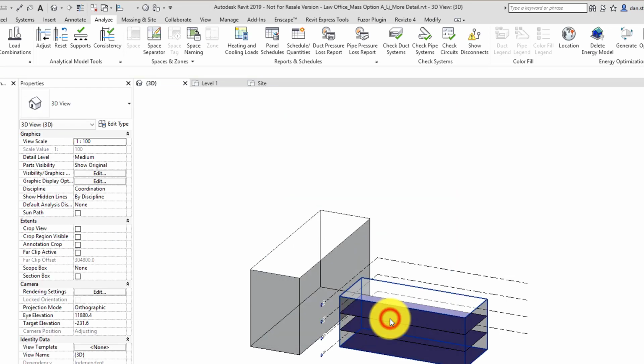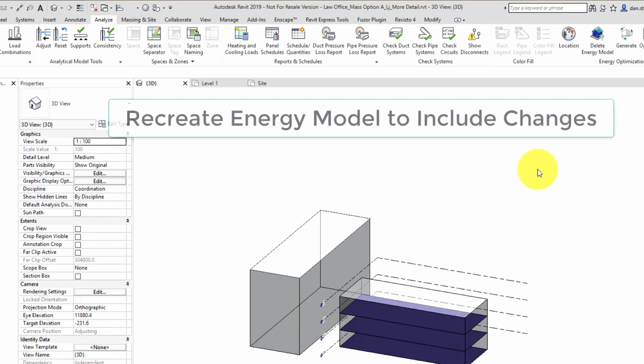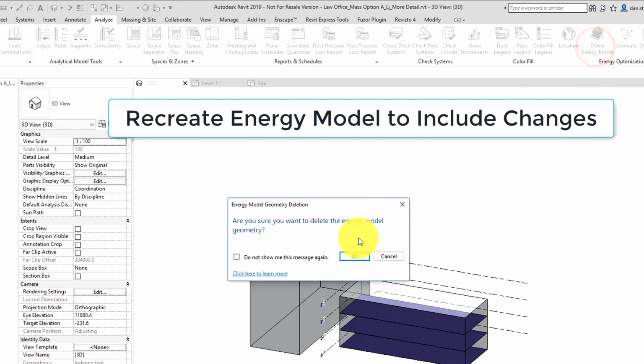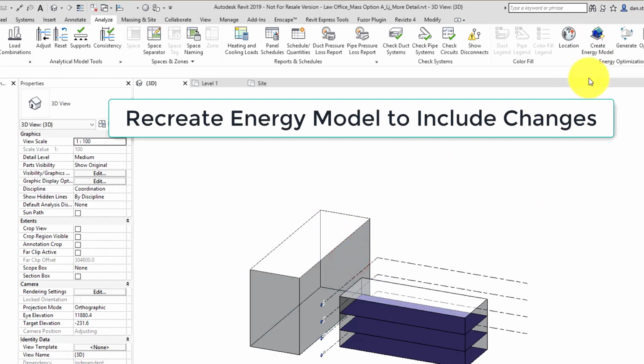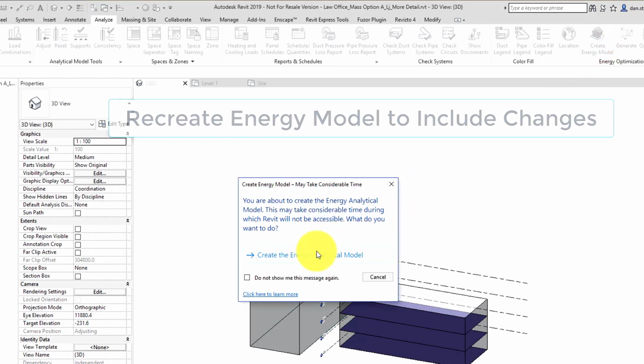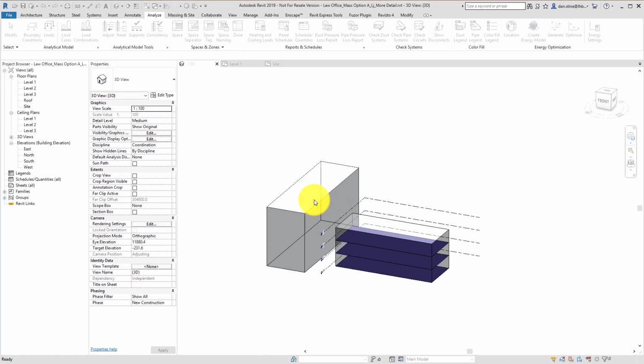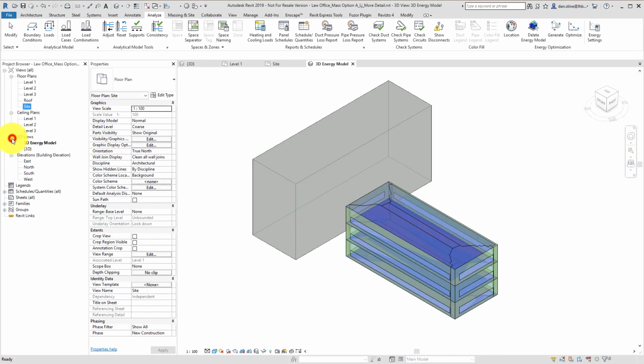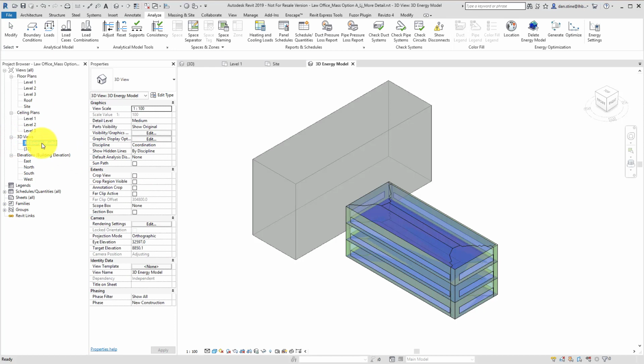Later I'll show you how we can get into more detail than the simple options that are listed there. But for now, based on adding the adjacent shade surface and specifying true north and adding the 30% window to wall ratio, we're going to create our energy model.